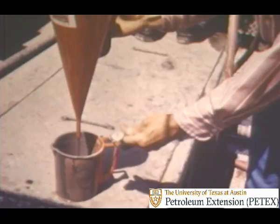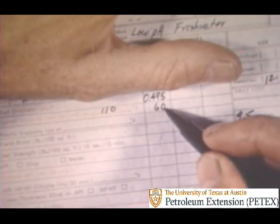Next, the mudman measures the mud's resistance to flow, its viscosity, with a Marsh funnel. He pours 1,500 milliliters, about a quart and a half, of mud into the funnel and times the number of seconds it takes for exactly 1 quart of mud to flow out of the funnel. We need to know the mud's viscosity because viscosity determines how easy or hard it is to pump the mud. He records the funnel or apparent viscosity and the temperature of the mud, in this case 60 seconds per quart, and 110 degrees on the form.